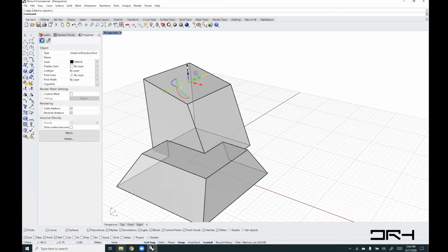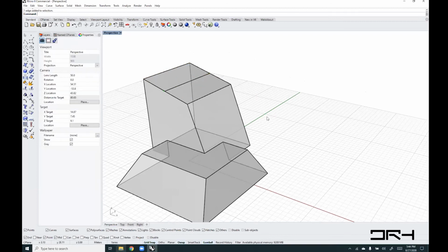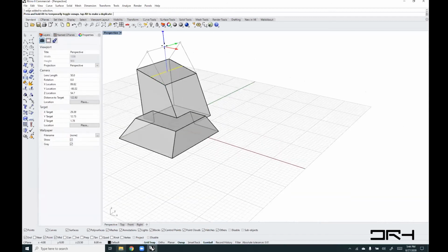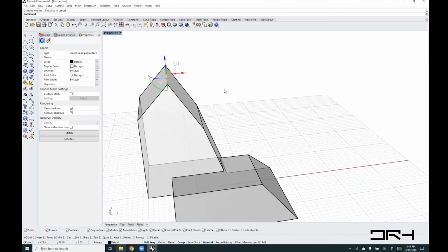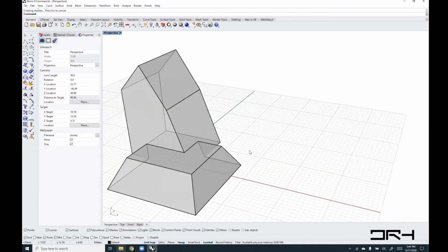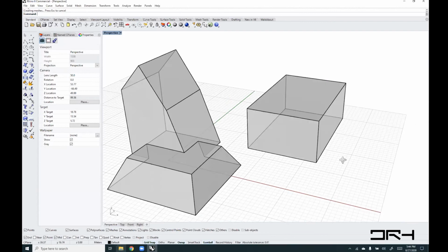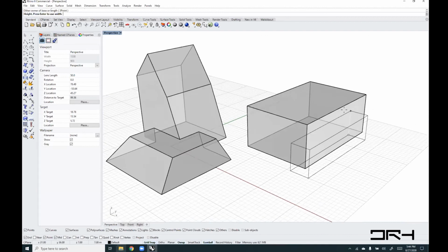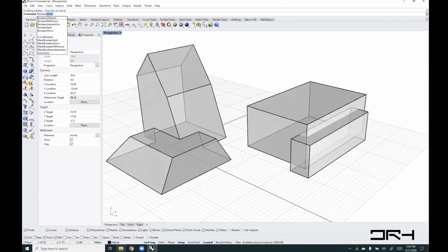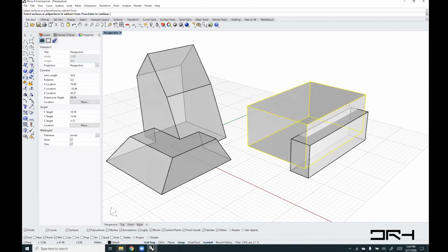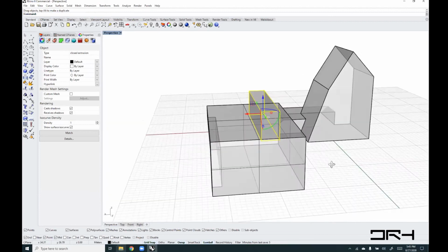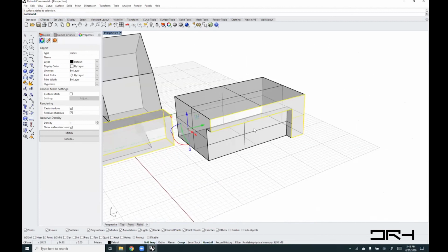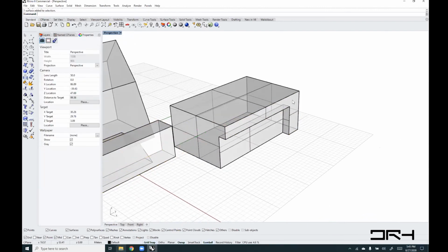Now it's going to make a little bit of a, let me try it on a box, easier, but well, let's be adventurous. So then you can create some kind of pitched roof really quick using this. But feel free to create certain kinds of geometry and start to subtract from your existing geometry, and then Boolean difference here. I'll just subtract this from that, and then that will generate this kind of object, and then you can select some of the faces and start moving them.